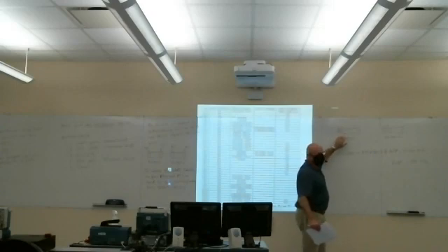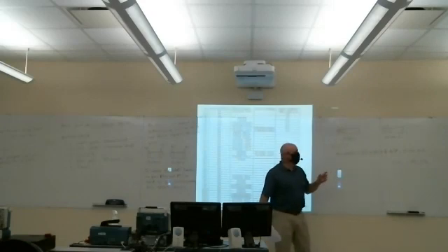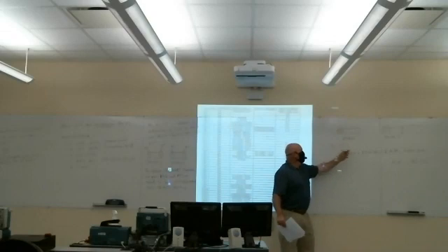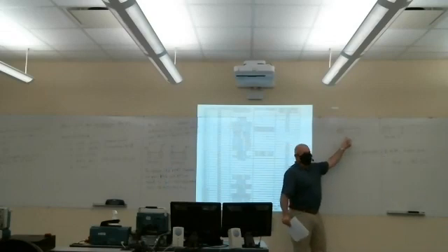They both may be zeros, they both may be 1s, they could be a 1 and a 0. It's going to read that value and AND it with 3F. So that would set those 2 corresponding bits to 0, and then we write it back to the register without changing any of the other values.